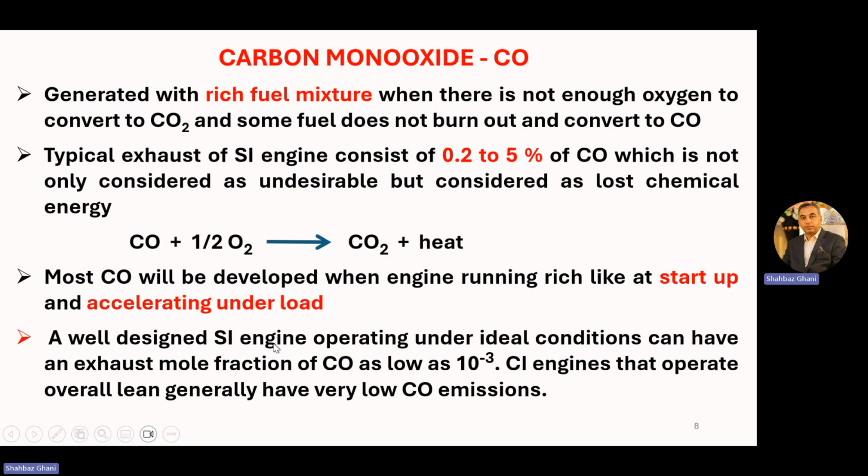A well-designed SI engine operating under ideal conditions can have an exhaust mole fraction of carbon monoxide as low as 10 raised to the power minus 3. CI engines that operate overall lean generally have very low carbon monoxide emission. So this is one plus point of the CI engine.